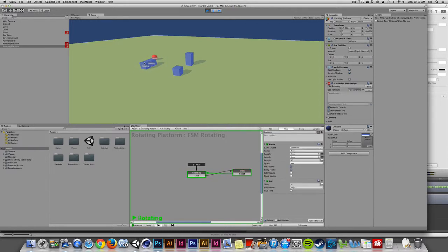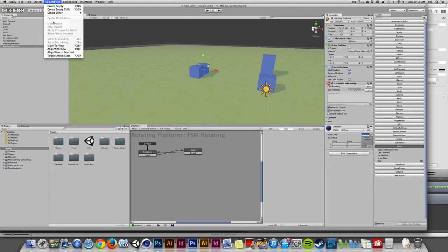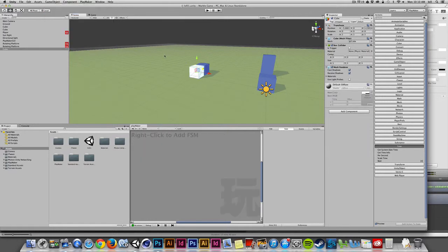Now, there's a couple of different ways that we could get away with building a ramp. We could, in really simple terms, just create a game object, create a cube. I'll take this cube and make it really small along the y-axis. I'll do 0.1, and I'll scale it either in the z or the x, depending on which direction we want to go. And then we can just do a rotation. In this case, we'll do like a 45-degree rotation, or maybe negative 45, or maybe negative 30. We can get the rotation figured out.